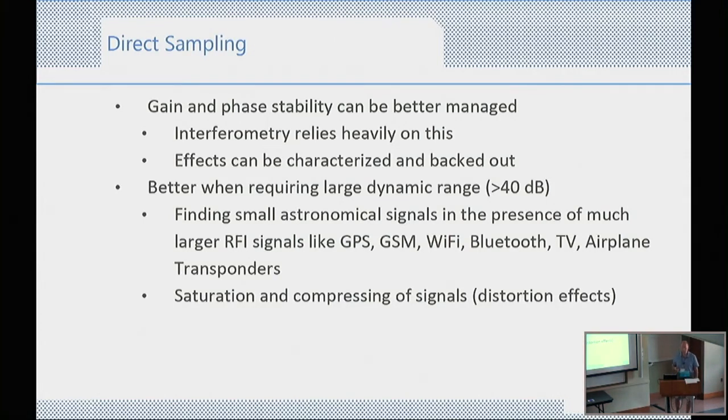Where there's RFI, you cannot get rid of that. A student asked me, okay, I understand this, but it still doesn't make sense to me. I said to him, imagine yourself standing in a dark cave looking at a small candlelight, and then I come with a huge spotlight shining into your eyes. That is sort of the effect of RFI. And strong signals can also cause your ADCs to saturate, and you can get compression of your signal, which also adds distortion.